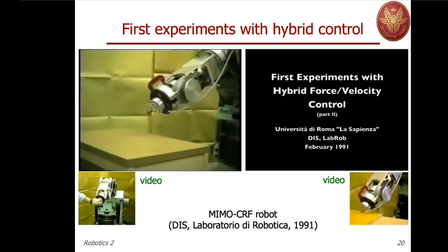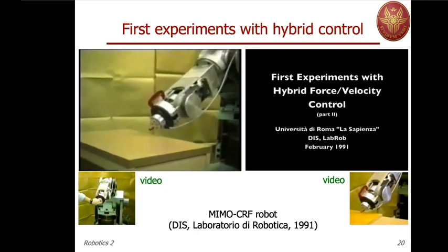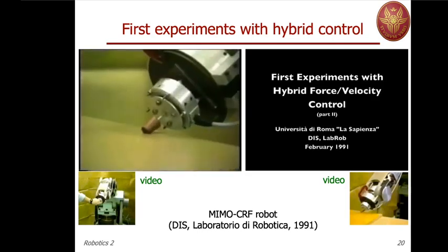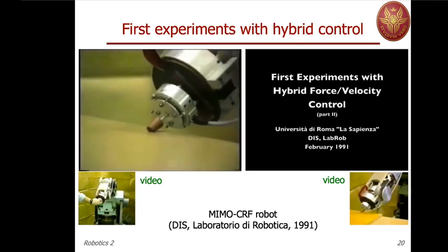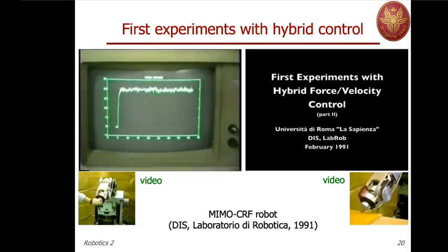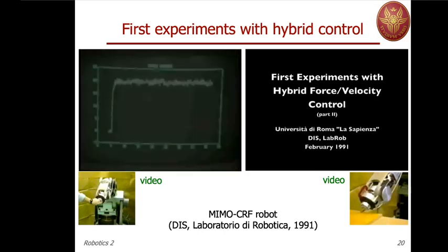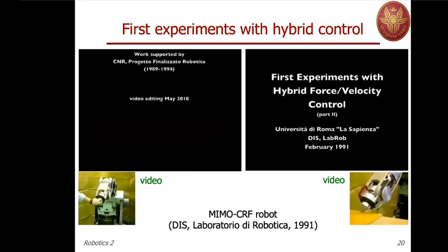are approaching exactly with the control that I showed before. In the approaching phase, we have a constant speed regulated by the damping parameter along that direction, and then we make contact and we apply, in this case I think it was, 20 Newton. Now, to understand how old this video is, you may see now some VCR screen from the IBM XT computer that we were using for programming the controller, and you see that the force had been regulated to 20 Newton after the initial transient approach.